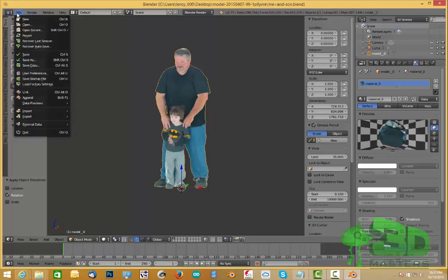To export it in the format that Meshmixer is going to edit it, we don't want any color on it. We want it to be completely blank when we do the editing, because loading color into Meshmixer is going to make it very difficult to edit. You could go through the hassle of disabling it, but why? Why work harder when you can work easier? These are free programs anyways.